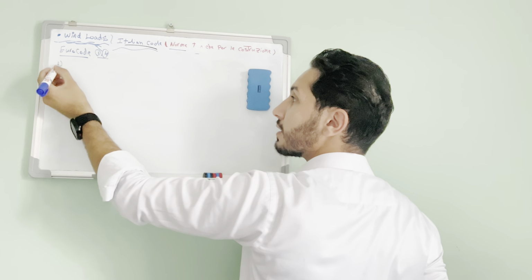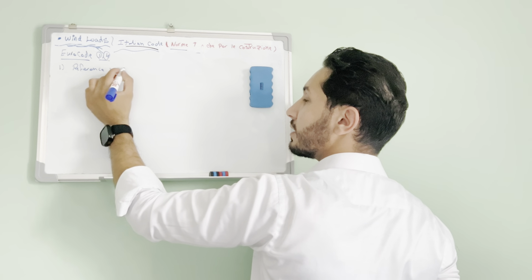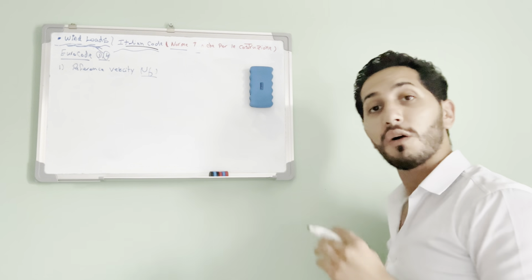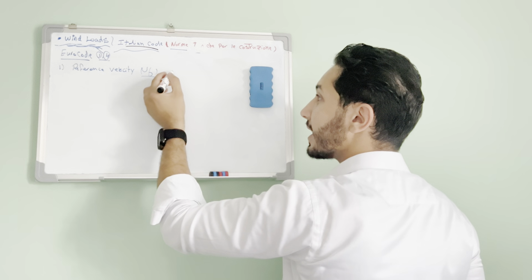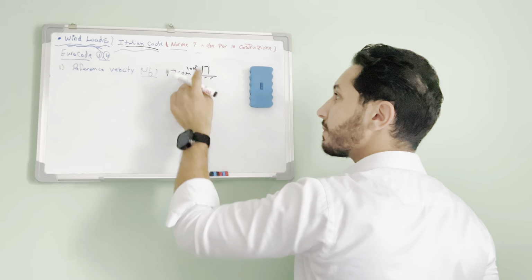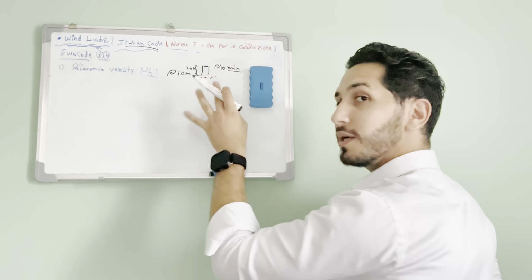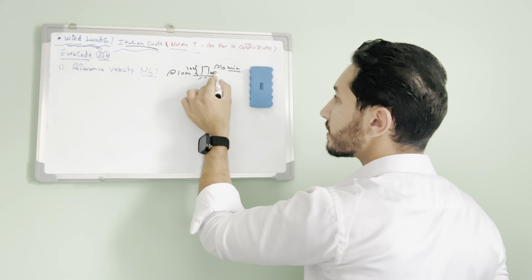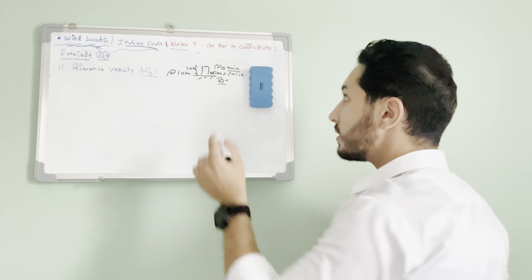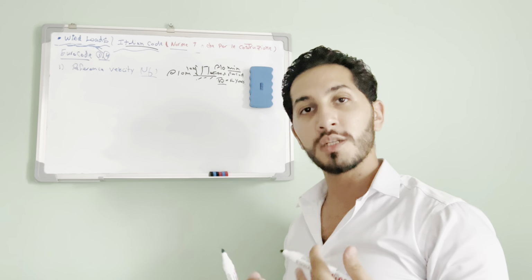The first factor we will have here is the reference velocity, VB. And VB is the velocity of the wind, or the wind speed, that acts at 10 meters height of the building. This VB is acting as 10 minutes of loading on the building for an assumed return period, which is TR, and we're going to speak about the TR later on, of 50 years. Or you can say 50 years of the construction phase and the usage phase of the building.